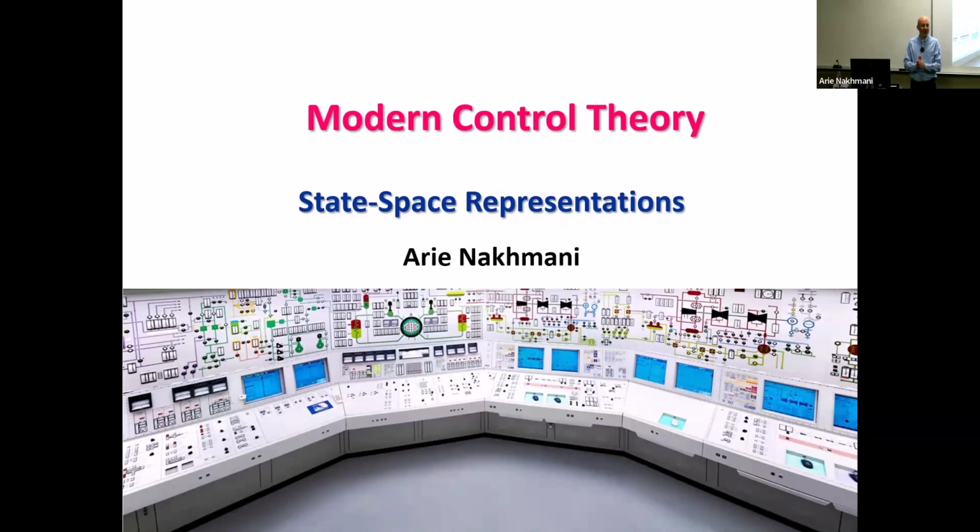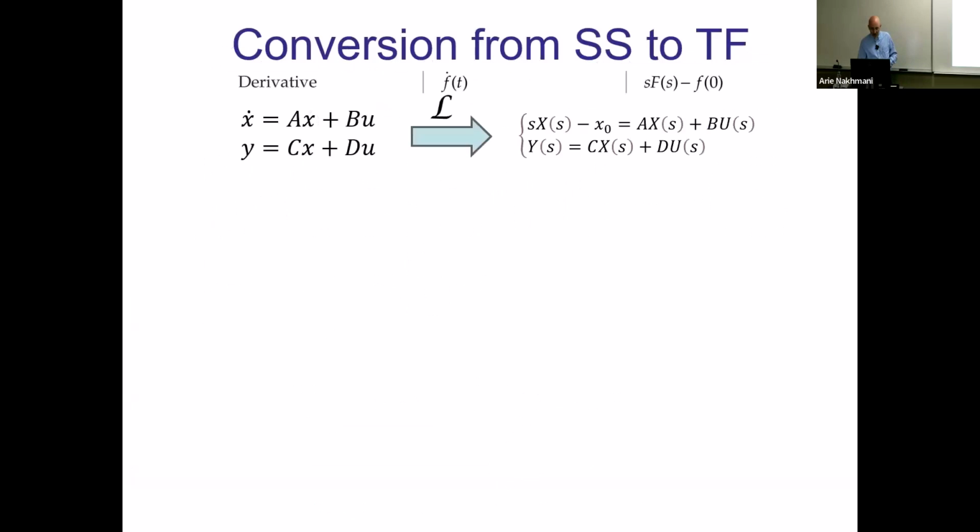So eigenvalues need to be in the left half-plane or in the unit circle, depending on whether it's continuous time or discrete time, for stability. And I'm talking here about asymptotic stability. For BIBO stability, you still need the transfer function or some other additional tools to understand if the system is BIBO stable. But for asymptotic stability, you're just checking eigenvalues. That's what you'll get before cancellation.